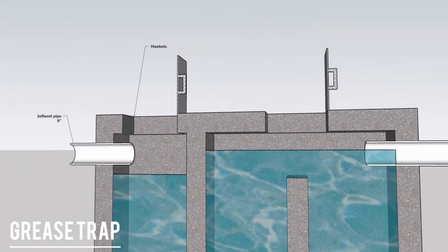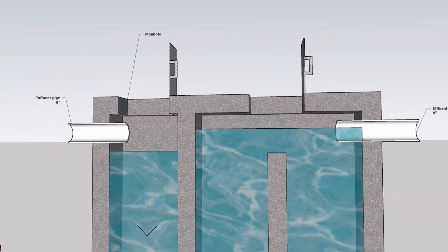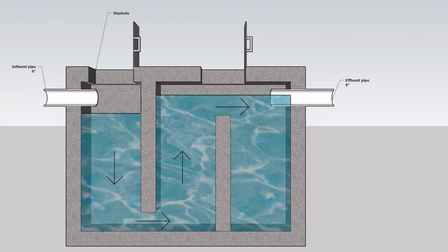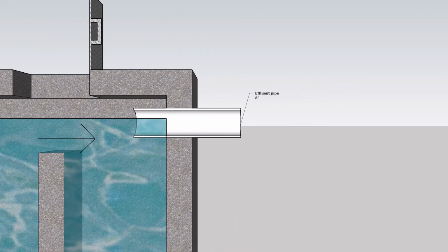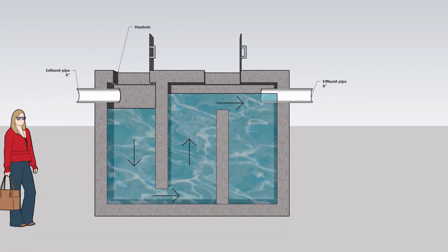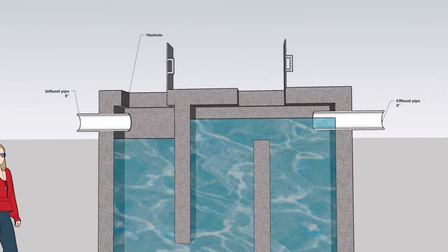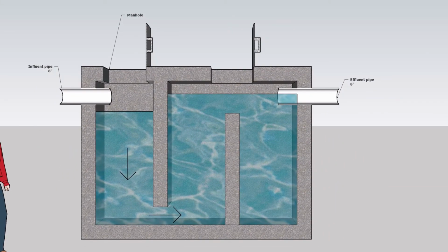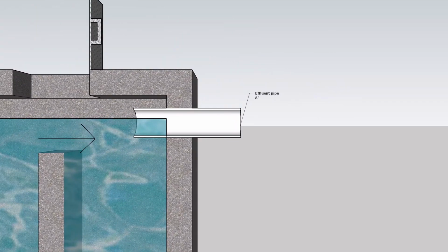First one is the grease trap. A concrete-based grease trap serves to prevent oil and fat which came from the cafeteria's waste from flowing within the wastewater, while wastewater from the other sources will continue to flow to the next unit, as shown in the picture, with fat being deposited at the bottom of the tub and the effluent flowing onto the effluent pipe. This unit is planned to be located 2.4 meters under the ground.